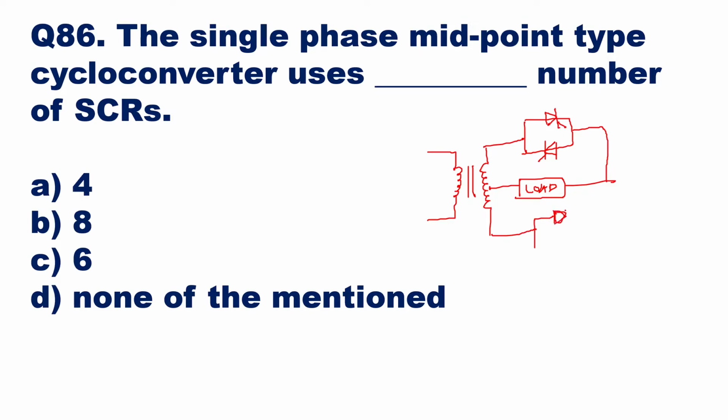One will be having a direction on one side and the other will be having a direction of the other side. So here you can have an inductor coil, and this is the input AC, and across the load you will get the output AC of desired frequency.